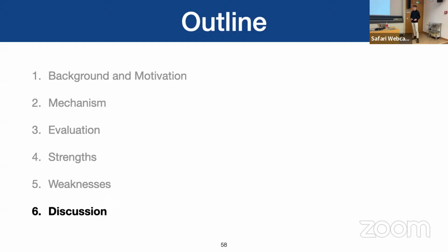Maybe Konstantinos, can you say where it comes from? Yeah, mainly because the tag cache and the set filter cache are, if I remember correctly, 4 kilobytes together, and this is compared to the L1 cache, it's 4 divided by 32, right? It's 32 kilobytes, let's say, the L1 cache. So this is a lot of area per core. A lot means 1% almost, right? But it's not negligible for sure. All right. Yeah, that's where it comes from.